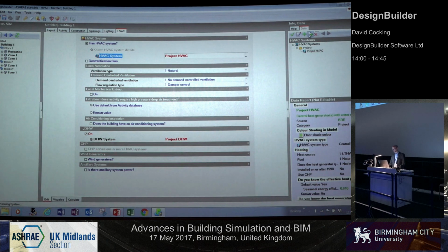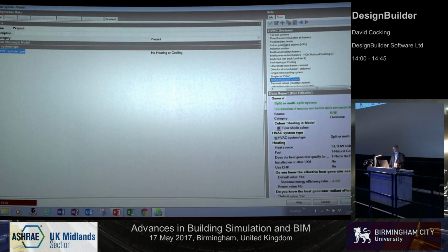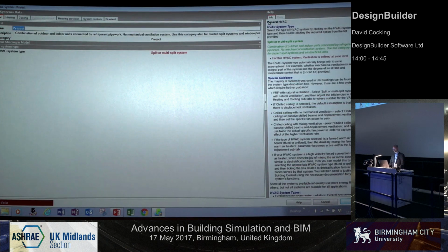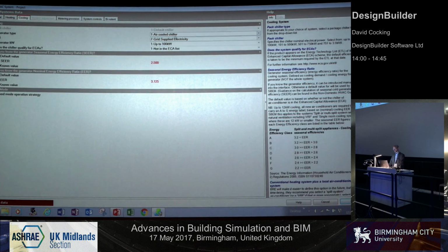So I can add a new HVAC system, choose the system type from the NCM list. Let's say it's a VRF system, small commercial building, perfect. So split or multi-split. I can assign an electric heat pump, grid supplied electricity. Let's say it's got a seasonal efficiency of 5. Define the cooling parameters. Again, VRF heat pump, electricity, and I can choose, let's say...